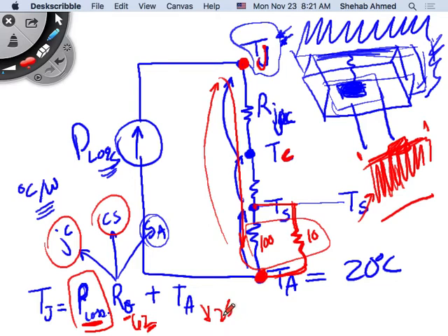Do they have chips that, whenever they get too hot, basically shut down? Yes, there are chips that have internal thermal shutdown. Obviously for downhole applications, we cannot use that. In applications where the temperature will be high, you will never be able to use these kinds of chips. So what we end up doing in applications like this is we screen everything. You can actually buy the same components from the vendor, screened to a higher temperature. There's lots of stuff that can be done, but again, we're talking about a commercial application perspective, where there are things that would shut down at temperature.